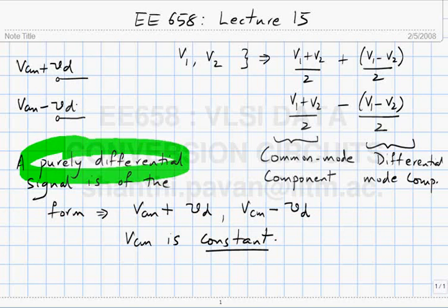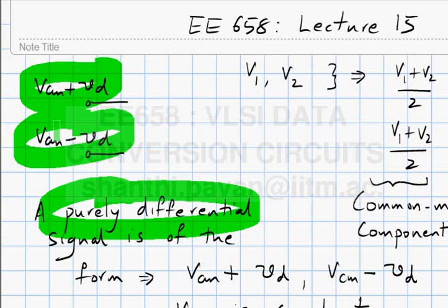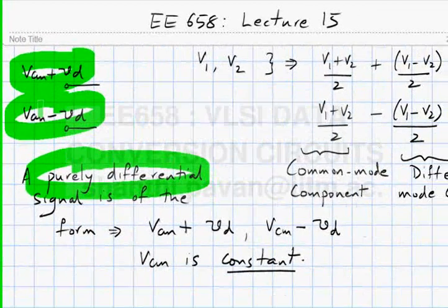If you didn't do anything deliberately to try and boost up the supply like we did in this Nakagome charge pump and so on, generally you can expect the voltages at any node to lie between 0 and VDD, or in this case 1.8 volts. So even though you have these two differential signals, the absolute potentials of both these nodes should always lie between 0 and 1.8, or VDD.